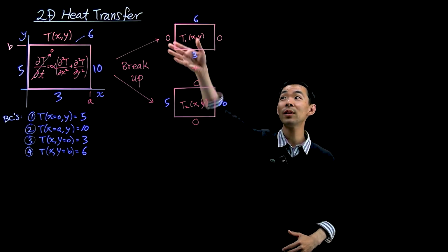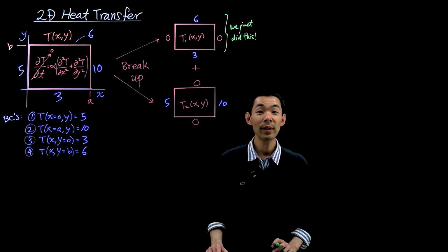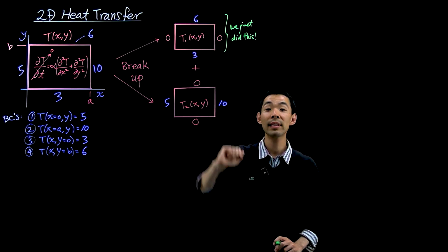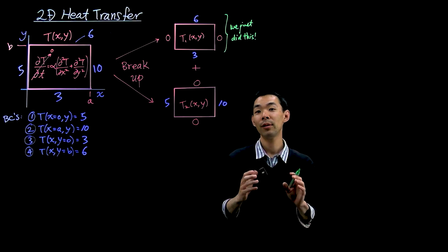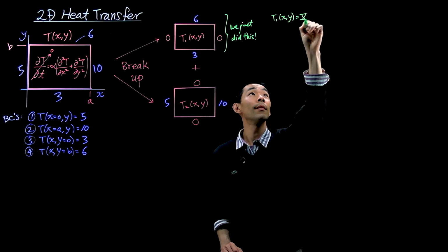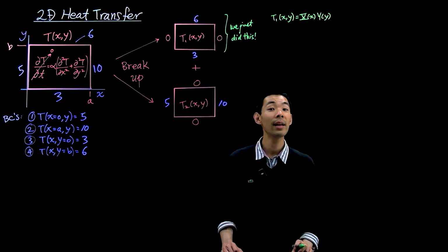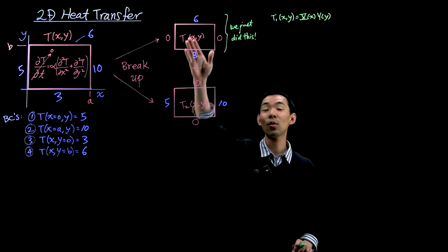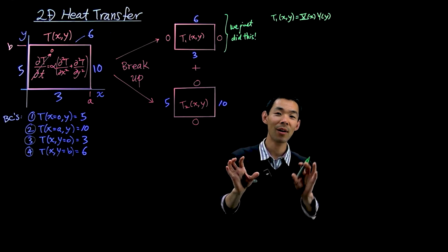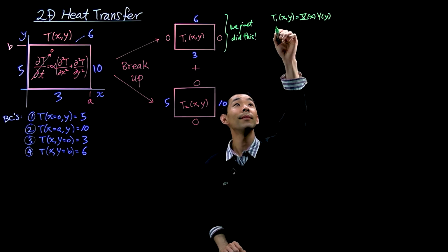So we can fully solve this problem. We just did that problem. What we did was we took our full solution T1, split that up using separation of variables into some function of x, some function of y. Just like that, we plugged it into the steady state heat equation. And then at the point where you separated all the x's, all the y's, it looked something like this.